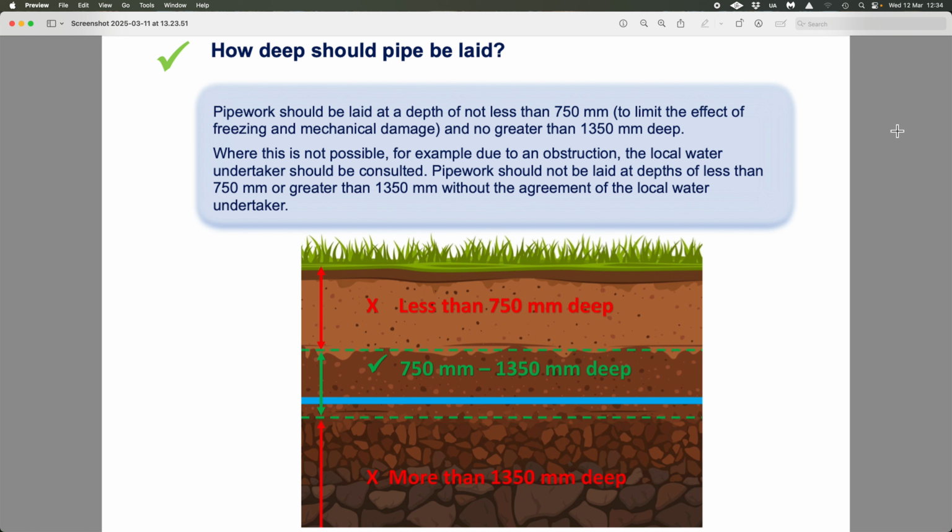We always buried everything at a metre deep. Now, why do we do that? Well, there's a few reasons, obviously, which make sense. The shallower that pipe work is, the more susceptible it is to temperature change or temperature difference, or delta T, if you like. That is the issue.